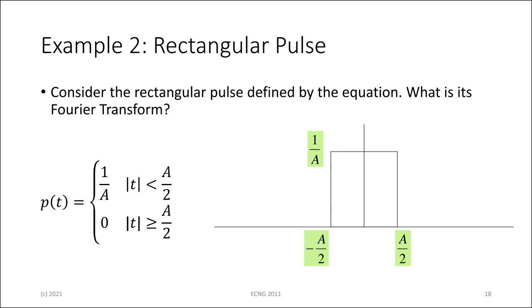It will saturate, you control the pulse in relation to whatever the saturation voltage of the op-amp is. Of course, you use a very, very fast op-amp too, so they can get the sort of sudden change that you want. So electronically it is possible to create a very, very narrow, very tall pulse.